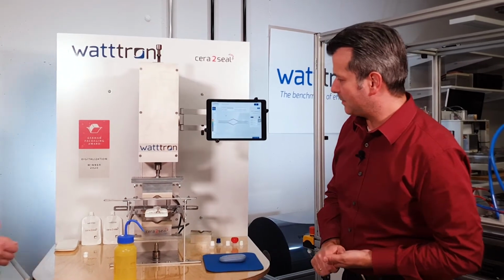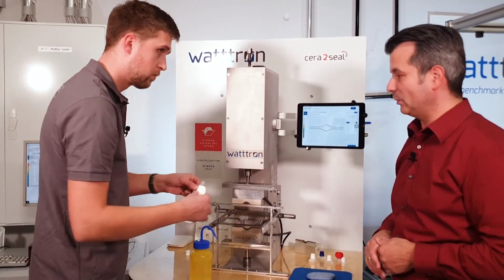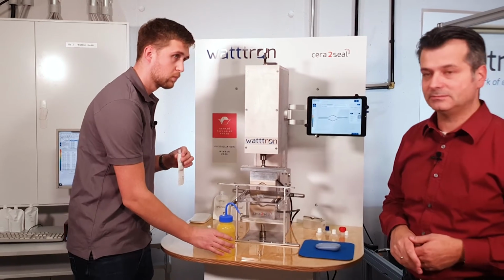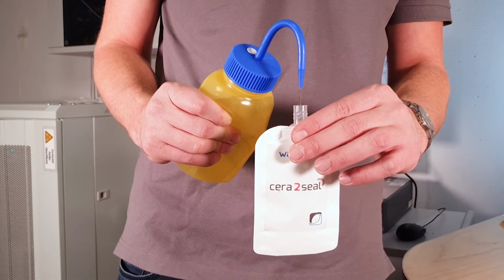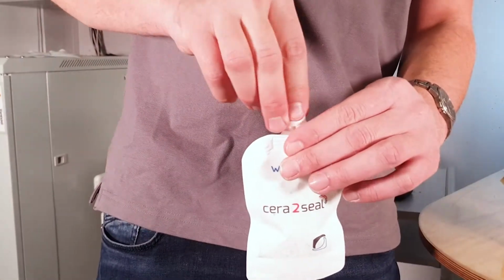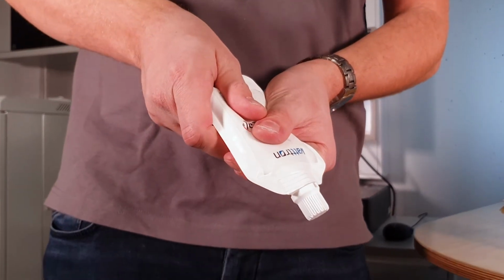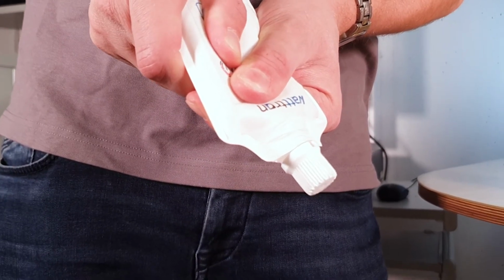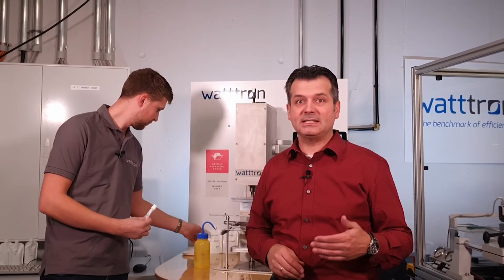So, as expected, I would expect now that we have a tight seal in the middle area, which we will prove through our water test, and a much better optical appearance in the rim area or the shoulder area of the pouch. Okay, as you can see, it works as I expected. The middle area, the spout area, is sealed tight, and the rim area has a good optical appearance a customer would accept, I think.